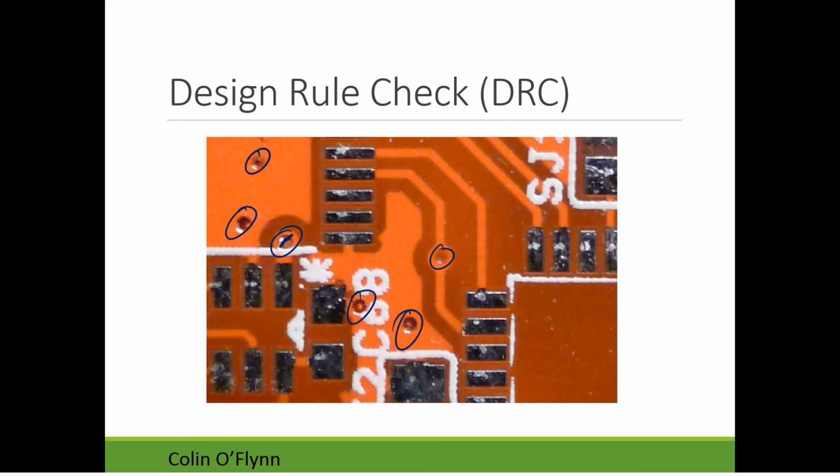And there may be other considerations like how thick. So you can see the silkscreen material here. You can see it's sort of looking a little bit dotty. It's not too bad. But as I try to make this text smaller and smaller, I'm going to lose the resolution, and it can no longer print that on the board.